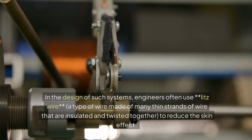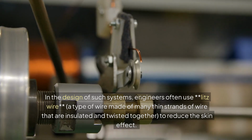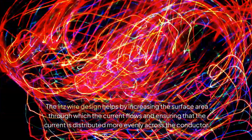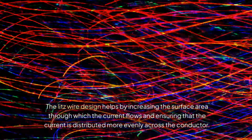In the design of such systems, engineers often use Litz wire, a type of wire made of many thin strands of wire that are insulated and twisted together, to reduce the skin effect. The Litz wire design helps by increasing the surface area through which the current flows and ensuring that the current is distributed more evenly across the conductor.